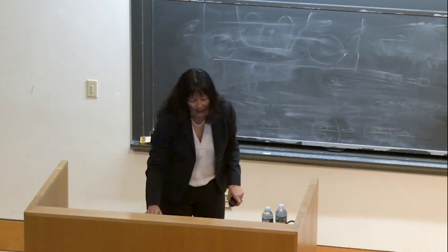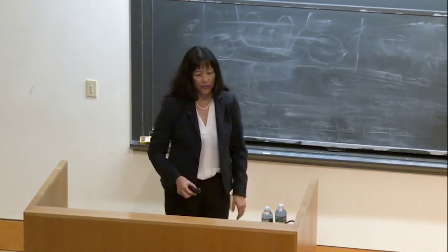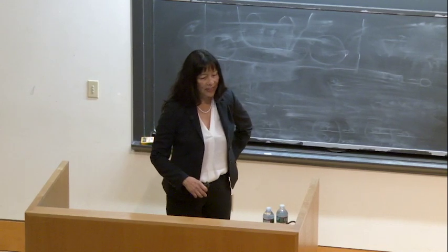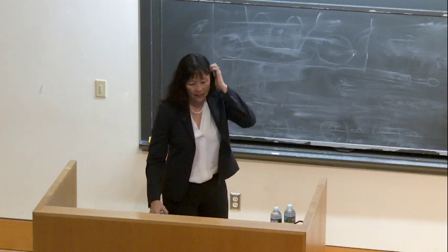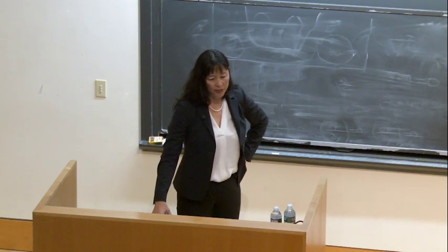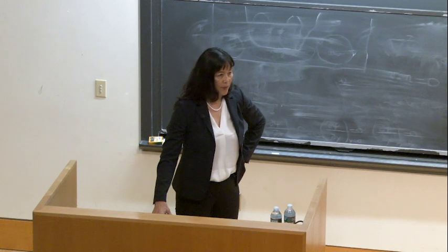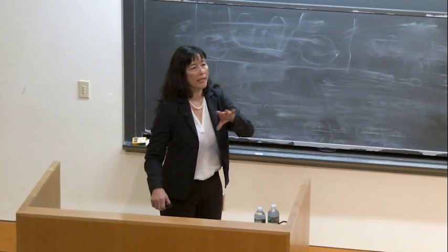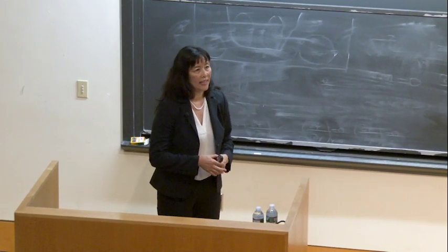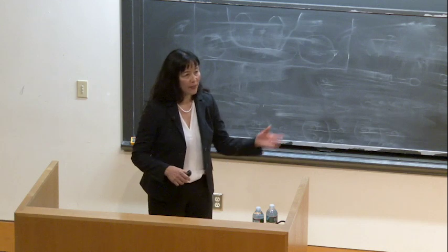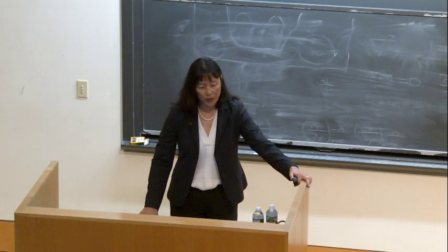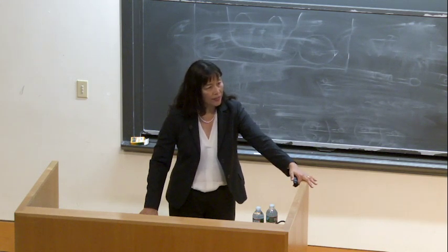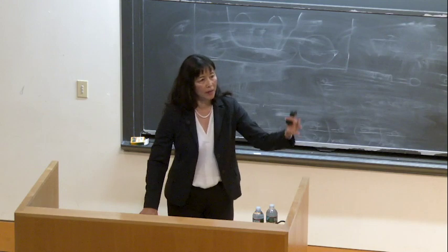Thank you. Okay, so, and then one last point of turbulence is that a healthy amount of it is good, especially when the fuel and oxidant are not mixed but separated. But if you strain it or you put too much turbulence on it, and the chemistry can't keep up, you can quench it. And so you have extinction either locally or globally. You can blow out a flame, and that would be really bad. For example, if you're in an airplane or high altitude, there's a whole bunch of issues that people are working on how to do relight at high altitudes if, for example, the flame goes out.